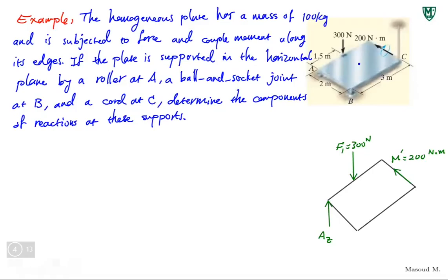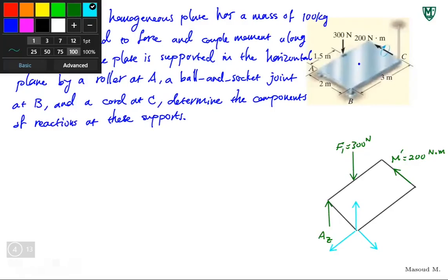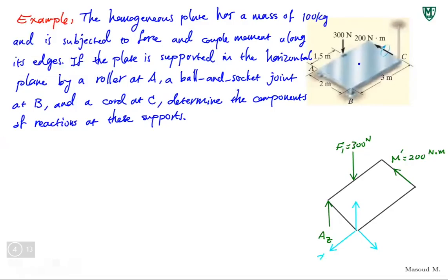Do you have any guess? B, right? Yeah, thank you, Richard. Make B your origin. Exactly. This is the best option because point B is going to have the most number of unknowns. B is a ball and socket joint and is going to introduce 3 unknowns to my system. So let's just use that. I have to follow my own advice, right? So let's put X, Y, and Z here. This would be X, this would be Y, and this would be Z. I'll put my origin there.